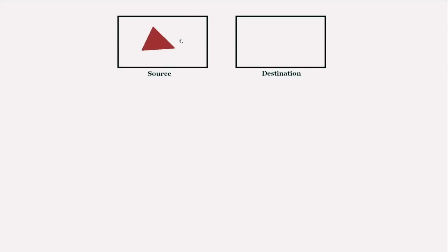So first of all, they can both draw polygons and fill them in. And so supposing you've done that in an off-screen region and you want to put it into a visible portion of video RAM. The traditional way of doing that is just to copy the bytes over one by one, to copy this rectangle into the destination region. Now that's going to be pretty slow because it'll tie up the CPU, and so it's nice to have a separate device that can do this for you. A so-called Bitblock Transfer device, or a Blitter for short.